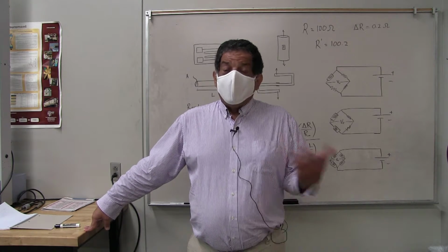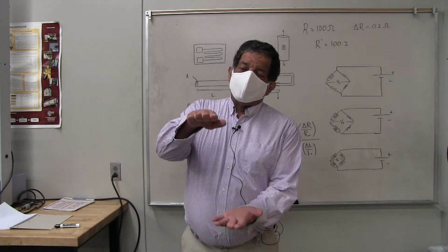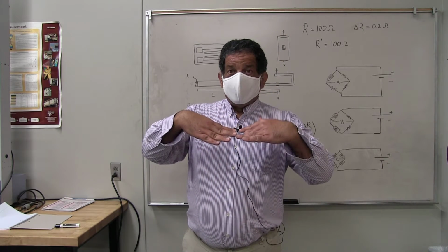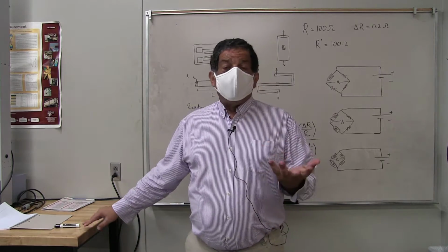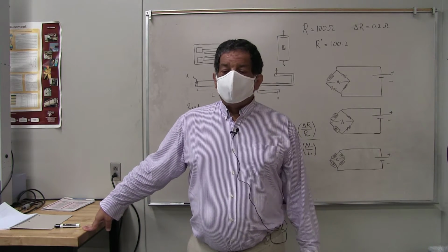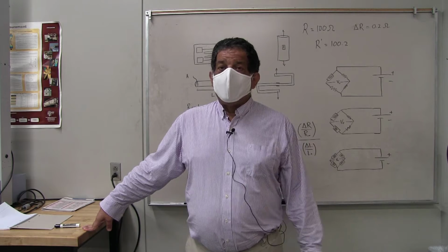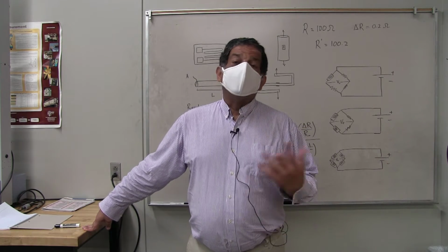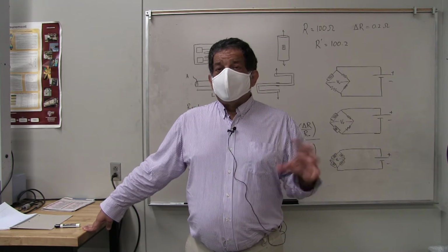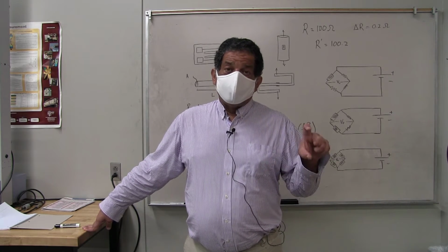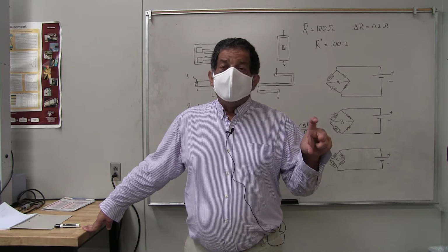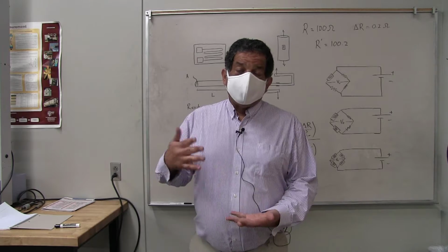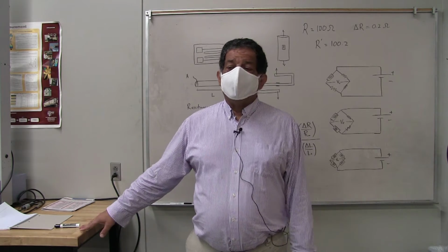And the advantage of the air ride is that because the rubber balloon compresses a long way compared to the relatively stiff leaf spring, you get a softer ride. So your objects which are fragile, if they're in the back of the truck, if you go over a pothole, they don't shatter. So that was the reason that they switched to this air ride. Plus it's an adjustable stiffness. By changing the air pressure inside that rubber balloon, you can get a stiffer ride or a softer ride. So it's got a lot of advantages.